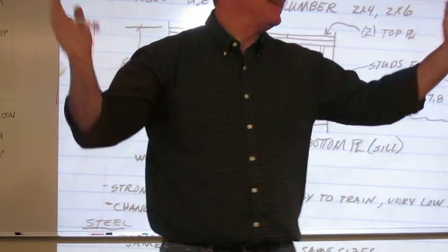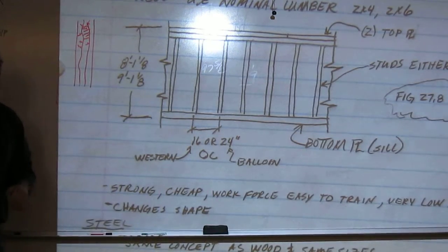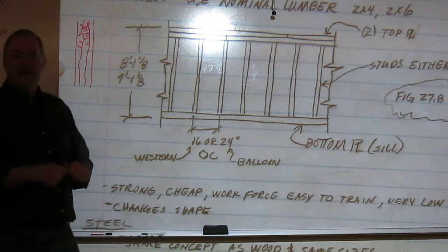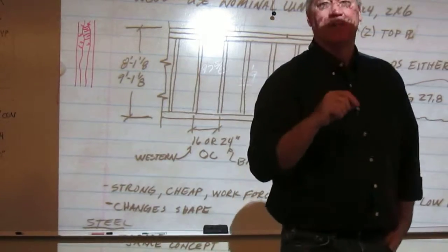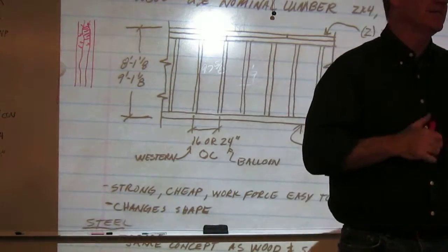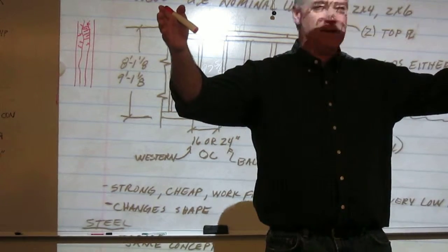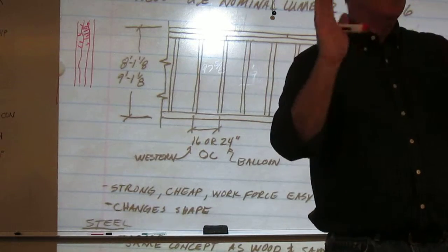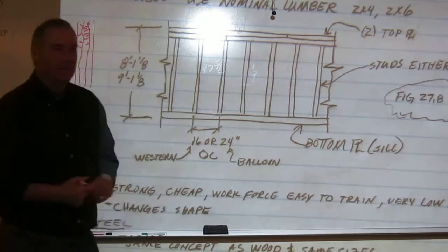Why would we have all these different spacings? It really depends. The 12 and 19.2 work better for joists. They match up with 4. All of those numbers, I should have said this first, divide into 4 feet evenly, so that I can attach drywall, 4-foot wide sheets, OSB, 4-foot wide sheets, and I put them on there and I don't have to cut them. That's what that spacing is there for.